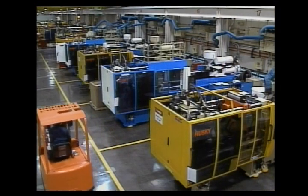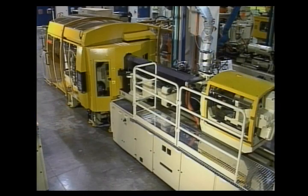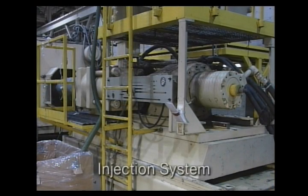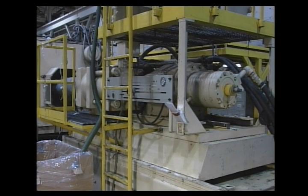There are an extensive variety of injection molding machines in use today. These machines are all a combination of two systems, an injection system and a clamping system. The injection system heats the thermoplastic material to its appropriate viscosity or flowability and then forcefully injects it into the mold.